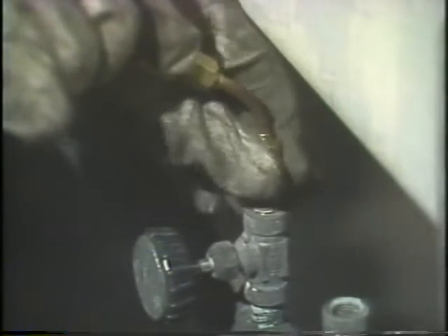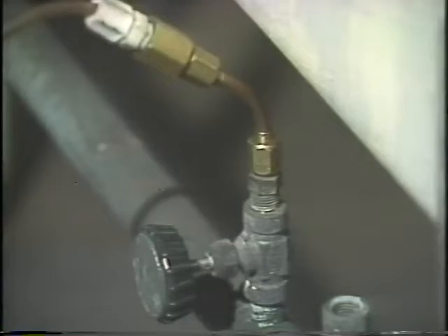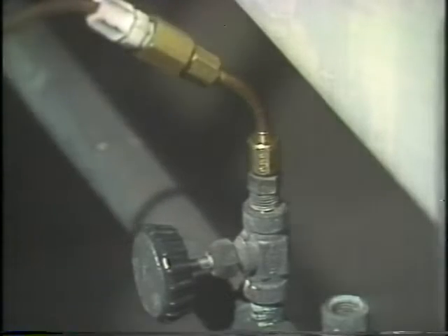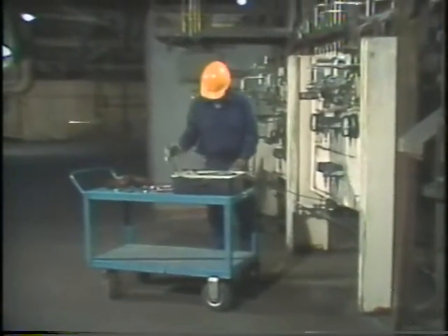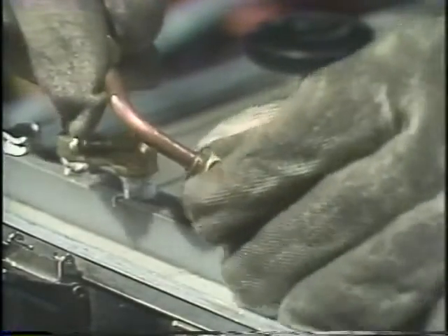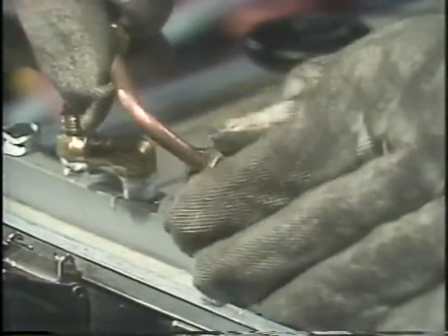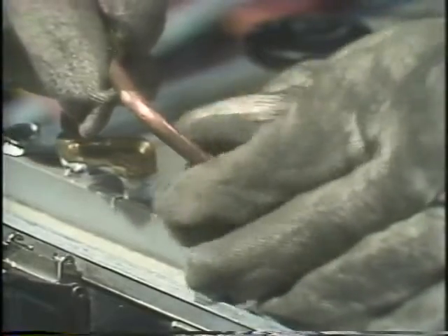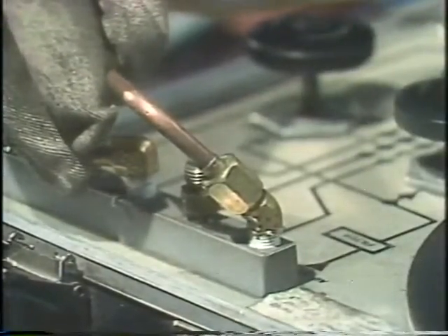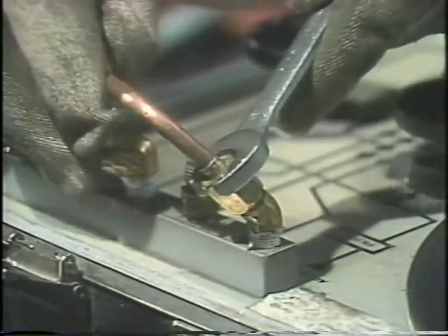I know this panel has a manifold along the bottom of it, and I can connect the calibrator to this air supply. I'll tighten down this fitting. There. And now I'll connect the other end of the tubing to the supply connection for the calibrator. That way I know I'll have an adequate air supply so that I can apply pressures to the transmitter. And I'll just snug this fitting now.